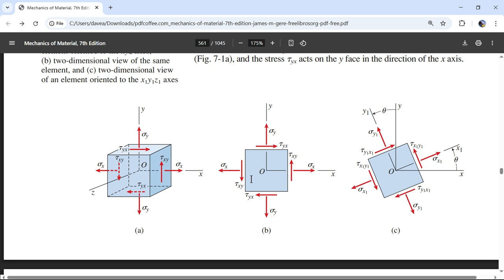But honestly, I wouldn't worry about beam convention when it comes to shear force, because you're trying to get this element, and this would be the positive y face, and this would be the positive new x direction. So I would throw away your conventions from beam bending when it comes to shear on this one.